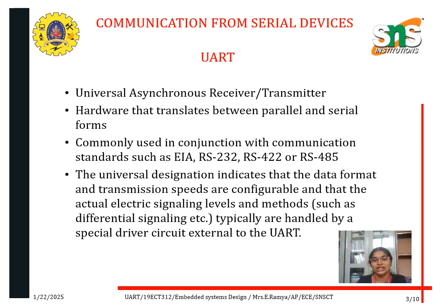It is commonly used in conjunction with communication standards such as EIA RS-232, RS-422, and RS-485. The universal designation indicates that the data format and transmission speeds are configurable, and that the actual electrical signaling levels and methods such as differential signaling are typically handled by a special driver circuit external to the UART.